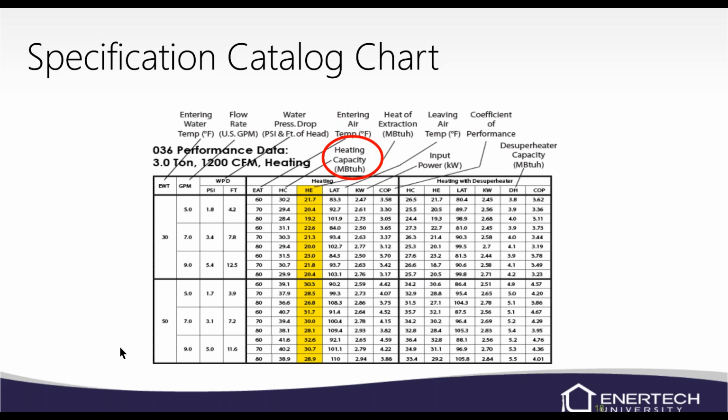We can actually figure out what the compressor is producing as far as heat. There's a formula: volts times amps equals watts. On a compressor, we can go to the contactor and check what our voltage is, probably 240, 230, somewhere around there. Then we can take an amp draw on the compressor. Let's say the compressor amp draw is 20 amps. We would take that 20 amps and multiply it by our volts, so 220 times our amps equals watts.